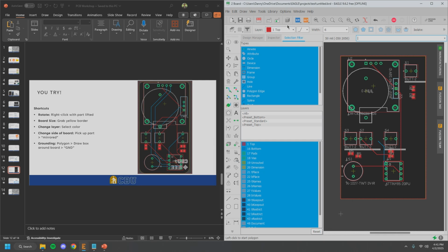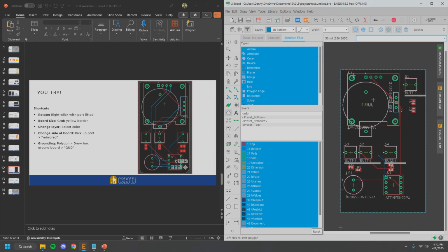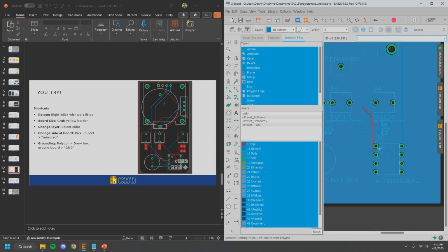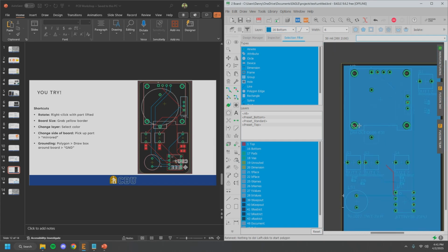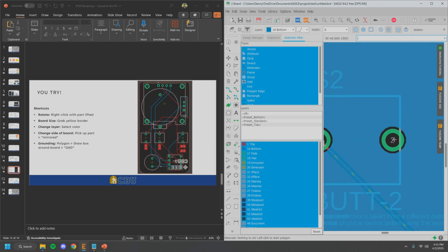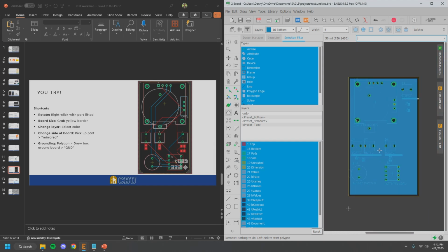And what that means is that we no longer need to make a physical connection to all the ground pins, because they are already all grounded if they are not connected otherwise. And so you're going to want to make sure that they do this for the top and the bottom. And now that entire board is grounded. So if I were to click on Rat's Nest, you won't really see it here because I did not connect ground to anything. But it would say, for example, if this button needs to be grounded right here, which I believe it is, then it would be connected to ground by default. So you no longer need to worry about actually making the physical connections to ground.